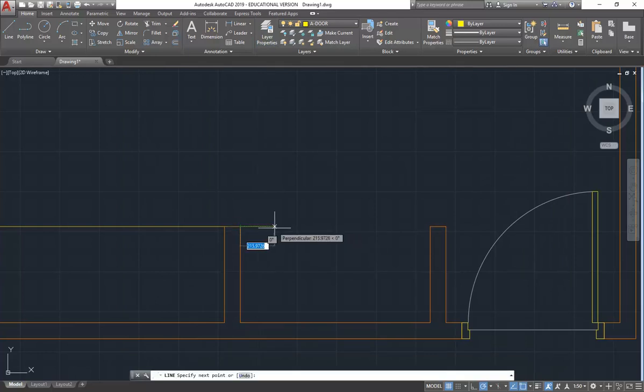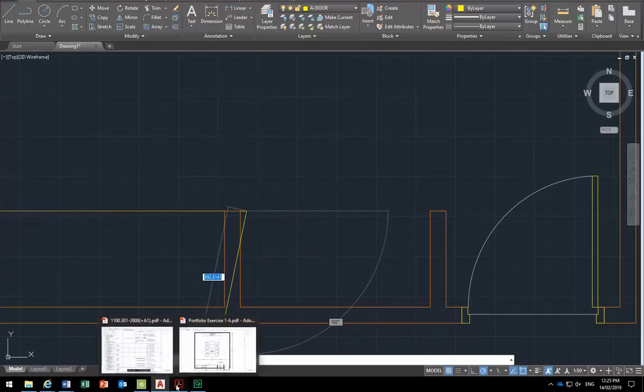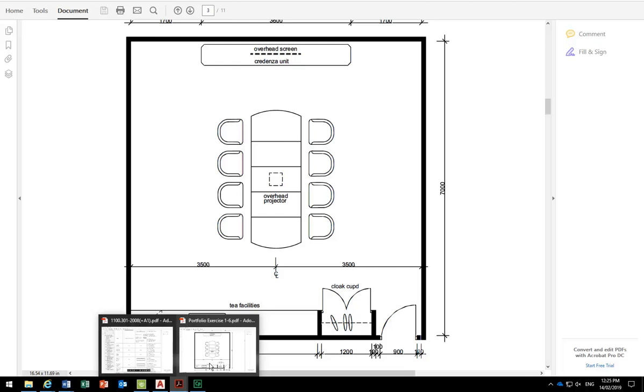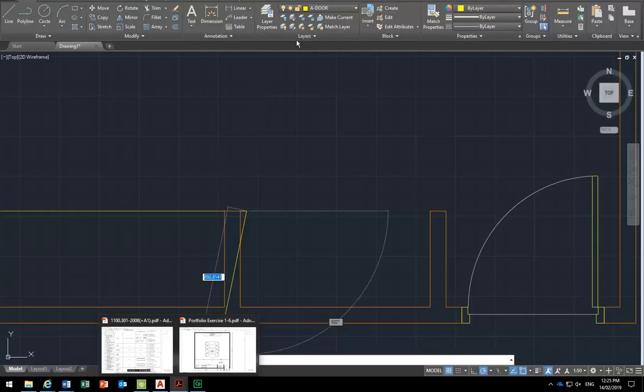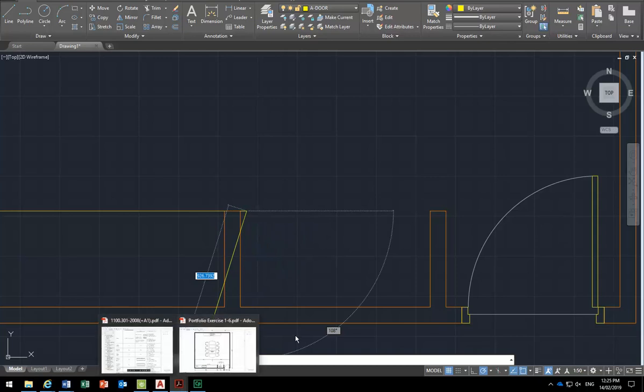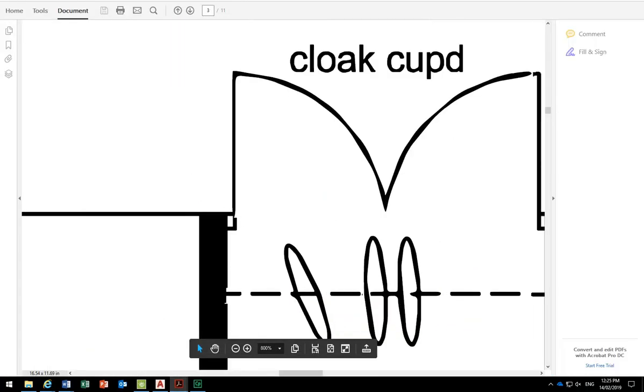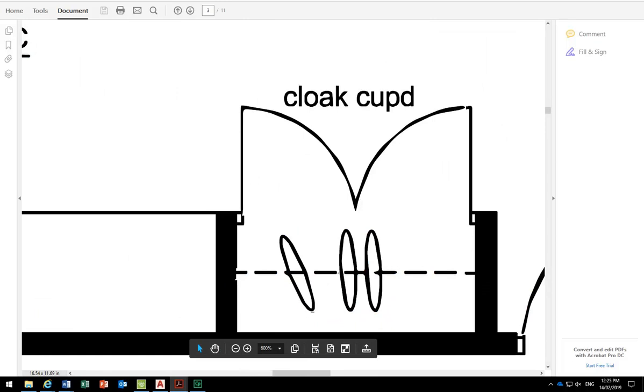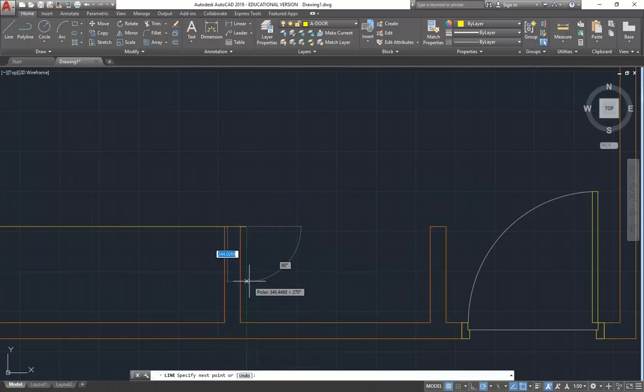So we're going to use 40mm as our standard jamb measurement, and because of the way it's been drawn in this exercise, yep, so if you're not sure, if you ever have to draw a door jamb and you're not given measurements, 40mm is the standard size. Normally 40 by 100, but looking closely at that drawing, you can see it's actually been done more as a square. 40mm across this way always. But that dimension, well, let's just do it the right way. I'm not going to draw what's there. That's probably about 60mm, but the more standard size is 40 by 100. So I'm just going to do that.